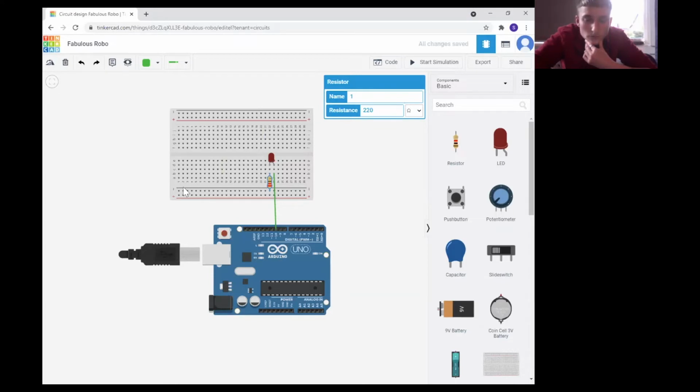And then one last thing to make a complete circuit. At the moment you'll remember I was very excited about complete circuits last time, Laura. The electricity has to be able to travel on a complete path. At the moment it goes from the Arduino up through the wire, through the LED, down through the resistor, and then it has nowhere to go. So we need to create that last bit.